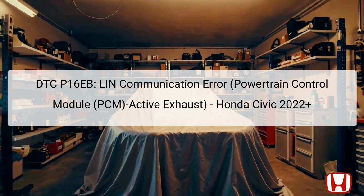If the PCM receives inaccurate information from the active exhaust valve actuator, it will flag this as an error, resulting in the P16EB code being stored. This indicates that the PCM is unable to communicate correctly with the active exhaust's LIN circuit. In this presentation, we will delve deep into the causes, effects, and precise troubleshooting steps to rectify the issues associated with this DTC. By following these guidelines, you can ensure systematic identification and resolution of the underlying problems.